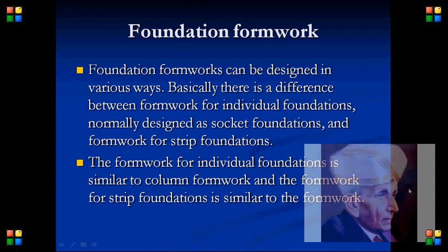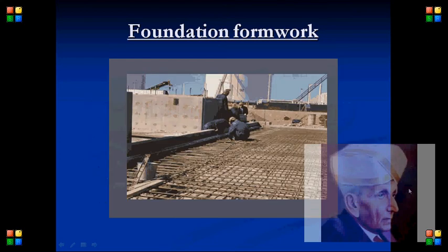Foundation formwork. Foundation formworks can be designed in various ways. Basically, there is a difference between formwork for individual foundations, normally designed as socket foundations, and formwork for strip foundations. The formwork for individual foundations is similar to column formwork, and the formwork for strip foundations is similar to the wall formwork.